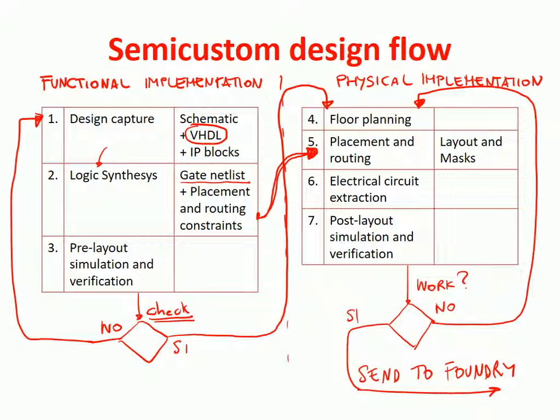And then we can be pretty confident that if the tools are in place and the models of the transistors and the models of the technology process are correct, then if it works in post-layout simulation, it will also work in the actual physical implementation. Okay, and this really requires that all the models that are used in the simulator are as accurate as really possible.